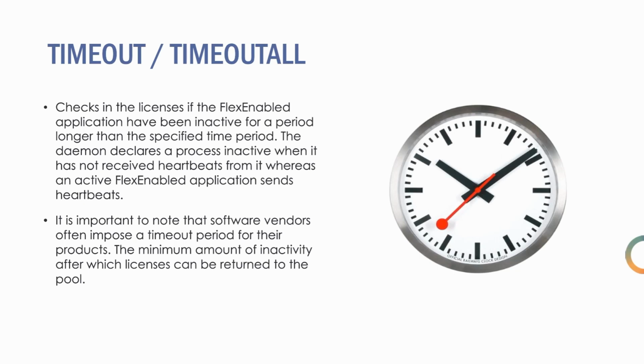There are other tools to return licenses so that they don't stay out there for 2 hours. However, if you set the timeout to a lower number than the 7200 seconds, which is 2 hours, then it might not have an effect depending on how the vendor daemon controls inactivity. So results may vary. This is a tough one to test because it's hard to hang a license. But if you end up with hung licenses and they're not coming back to the pool very quickly, take a look at TIMEOUTALL.